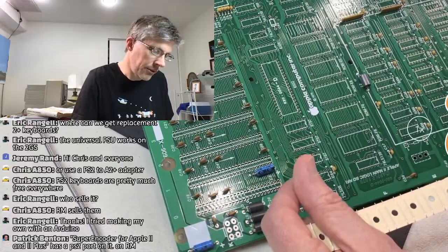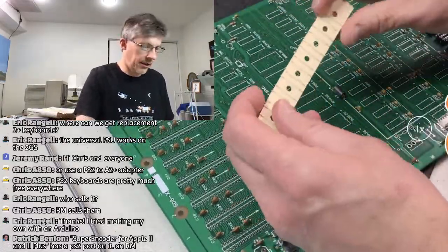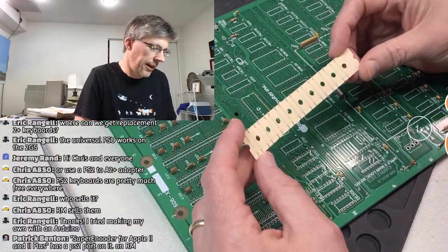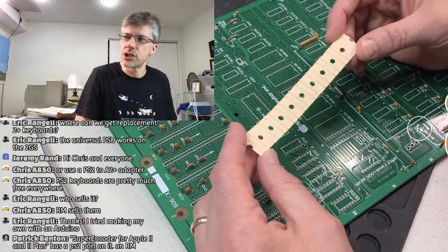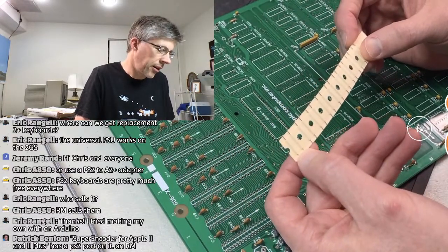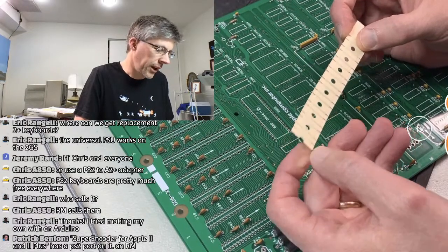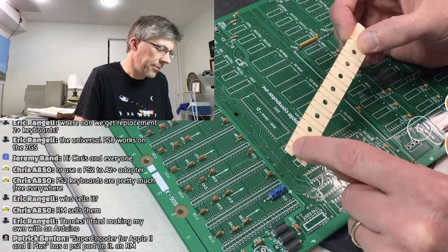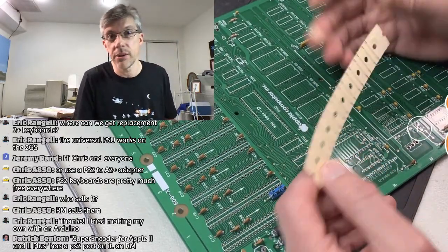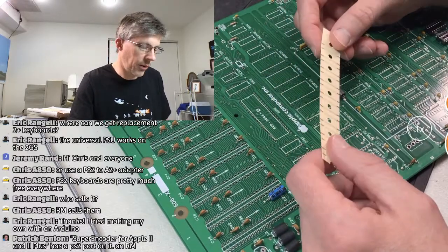There are a few gotchas to watch out for. First of all, let's see if you can see this. The capacitors come on sheets where the metal leads are just taped down. They're almost impossible to get out of there. It's not worth the effort. So what I did is I just clipped them at the top. That makes the leads a little bit shorter, but it doesn't matter because you're going to cut them off anyway once you solder it. So that's no big deal. Just be aware of that.